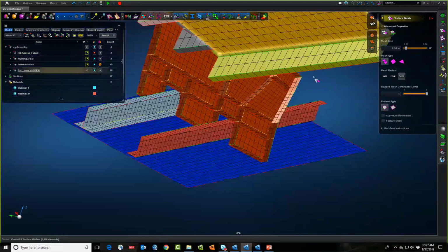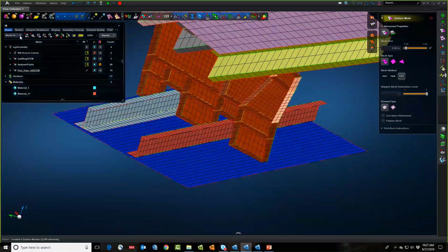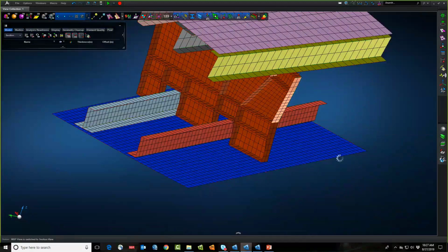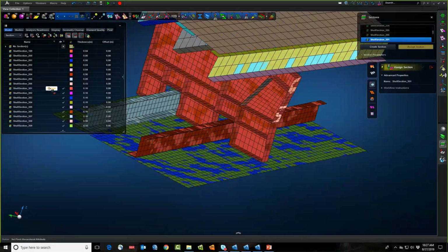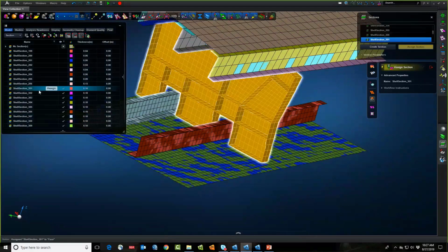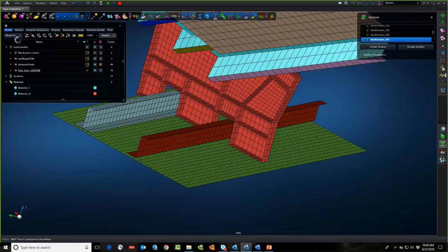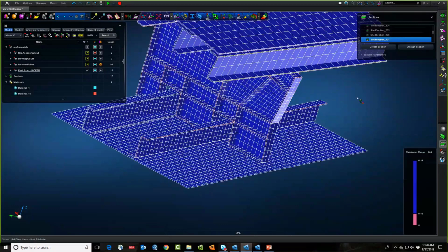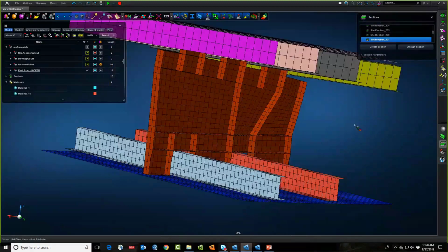So let's actually put a thickness on that, and I want the thickness to be the same thickness as everything else that's in the rib. That's easy to do in Apex by going to the section view. When I go to the section view, I can select the thickness that's assigned to the rib, and I can actually assign that thickness very, very quickly to my flange, which was, of course, new. And I will validate very quickly by turning on the 3D thickness again, and I can totally see that, okay, I do have a thickness there. So once again, I started from an orphan mesh, and I am creating something new effectively, reusing, repurposing, redesigning, re-engineering at this point.